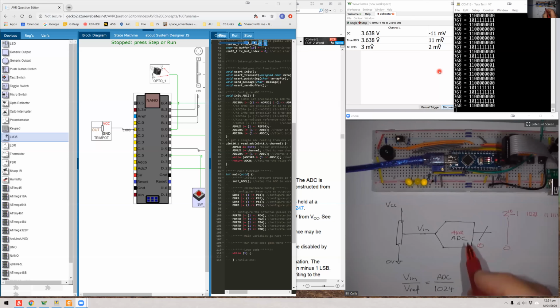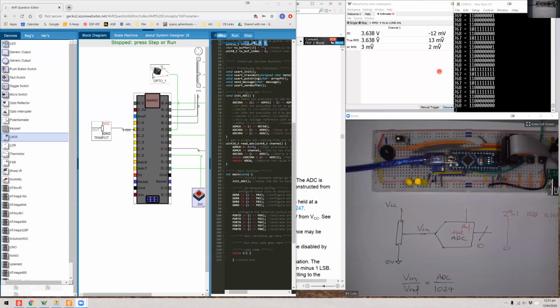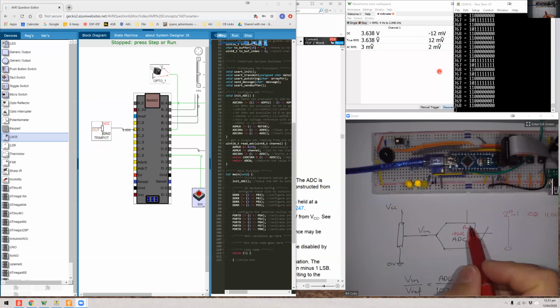Now, our reference voltage isn't shown. We have a pin here called AREF. Now, AREF is what we use as our reference voltage. Now, we also, of course, have 0 volts here. So these are connected. And our reference voltage, well, let's have a look at the data sheet.